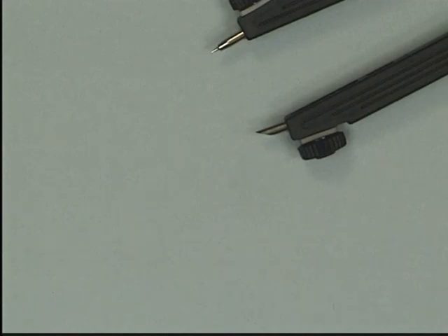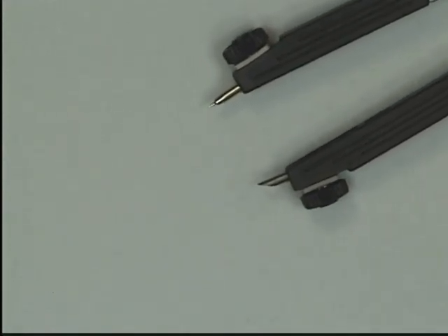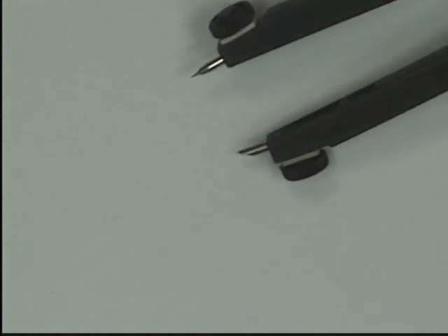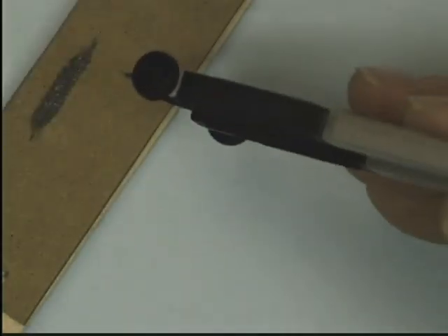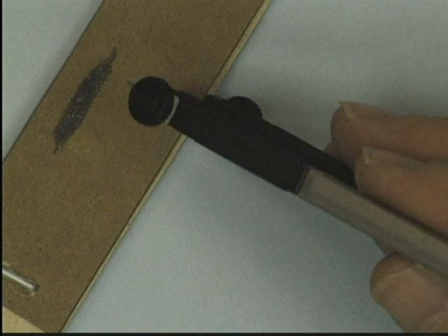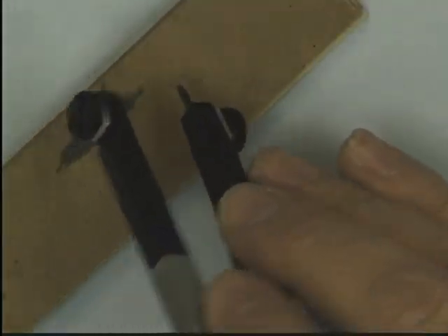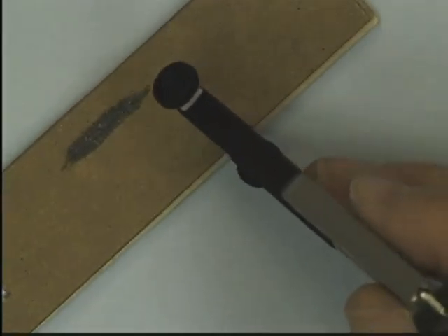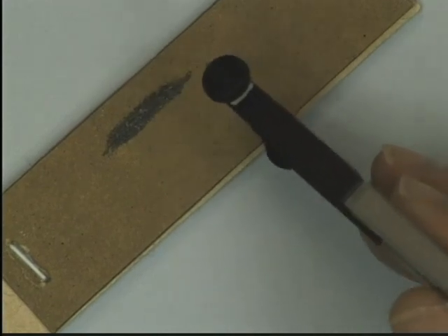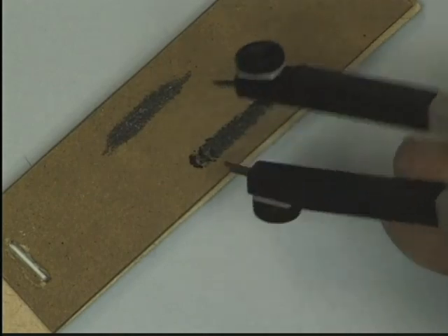The point on the compass is not a conical point like it is on a drawing pencil, but it's sharpened to this wedge shape. And the way we do that is we use a little sandpaper pad, and then we hold the lead a certain way. First of all, we want to hold it at an angle of about 60 degrees to the vertical. And then, not twisting sideways, we want to maintain this perpendicular to the sandpaper pad. And then we scrub that back and forth until we get this nice wedge shape point.